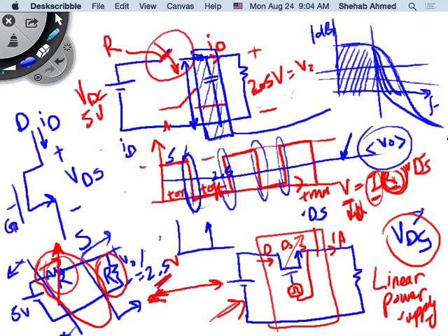But am I eliminating them? No. There's always something called ripple in a power supply. In a power electronics power supply, even though I've done a decent job designing my filter stage, I will always have some sort of ripple. This ripple is also a spec of a power electronics power supply. You will typically be given not just a certain input voltage and a certain output voltage, but also a certain ripple spec. That ripple spec will tell you how to design your filter, because based on the way I design my filter, the ripple content will change.